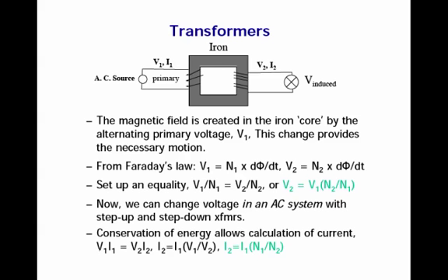So how does this work with the conservation of energy? When I step up voltage, do I step up power? Am I creating power? Am I increasing power? Of course, we can't do that. So if the voltage steps up, the current must step down. So when you draw 1 amp here, you'll have to produce 2 amps over here in order to supply you with your 1 amp. So if the voltage is stepped up, N2 over N1, the current is going to be stepped down, N1 over N2.